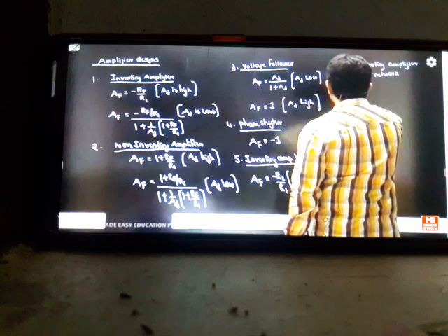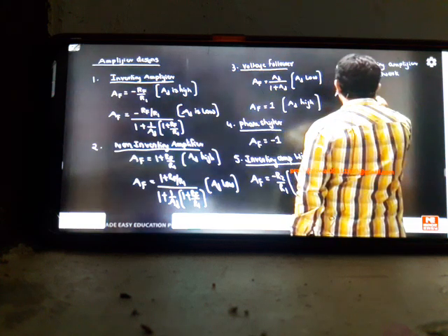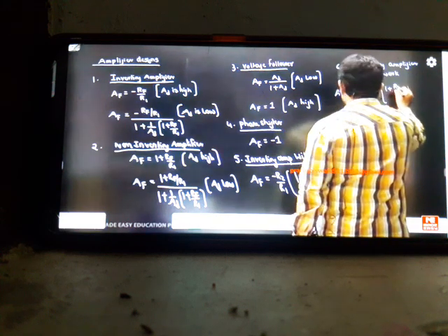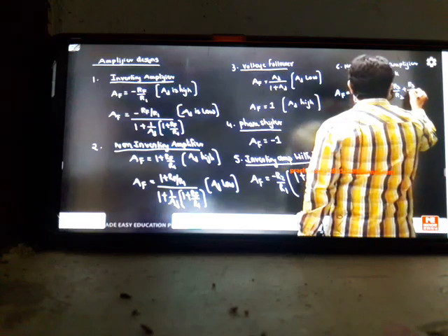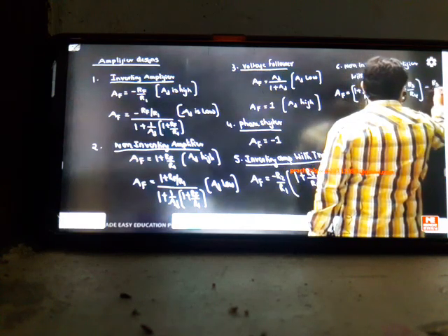So the formula is something different here. It is 1 plus R2 by R1, the non-inverting gain, into the same quantity we have to write: 1 plus R3 by R2 plus R3 by R4 minus R3 by R2. So you can see the structure.